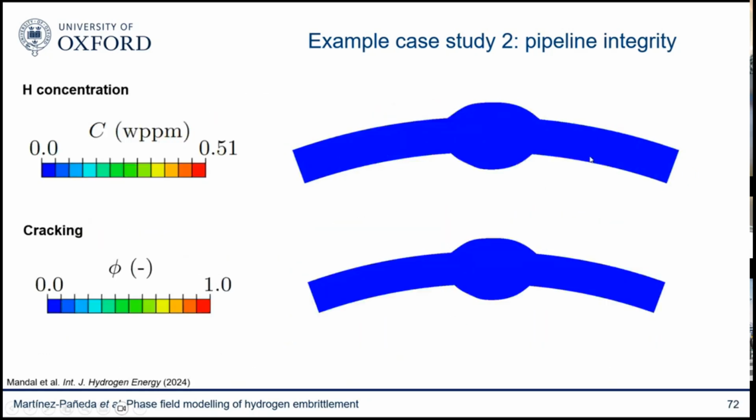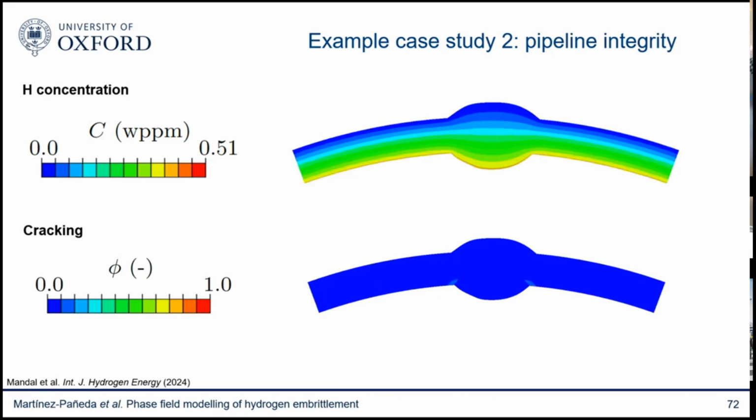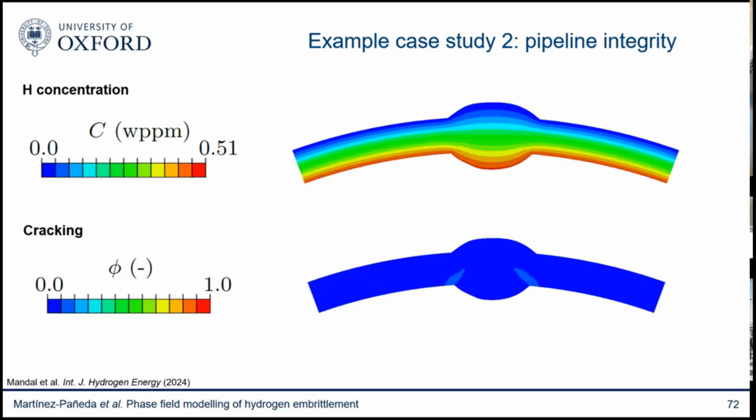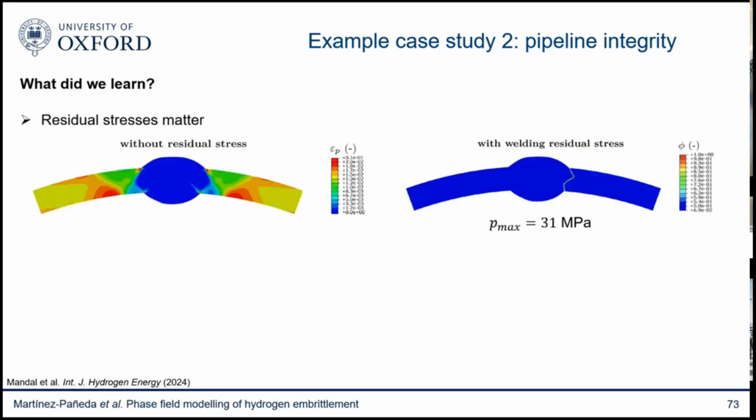But basically what we do is we increase the pressure, and then we see how failure happens. And failure can happen one of 2 ways. It could be that your entire pipeline will collapse due to plastic collapse, so you have plasticity all over the place. The other option is what you see here. Eventually, you trigger a crack. So we consider one case as plastic collapse, and if plastic collapse happens before cracking, that's the end of the calculation. We say, this is a too high pressure. They're not going to use this in practical applications. But if cracking happens before plastic collapse, we say, oh, careful. Engineers probably did not design pipes for this scenario.